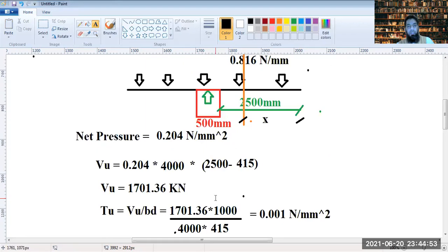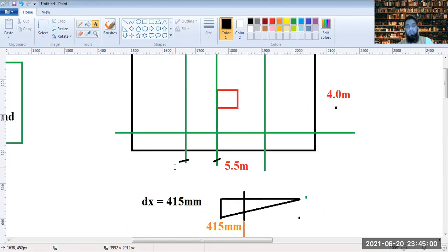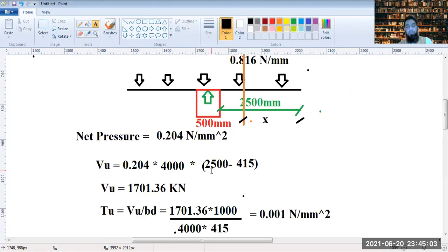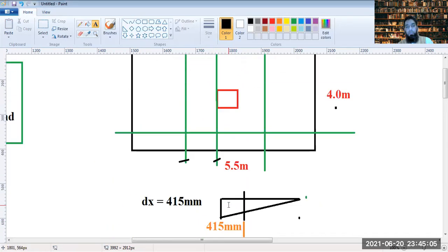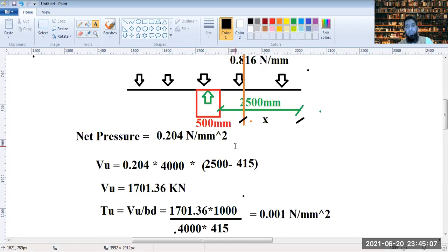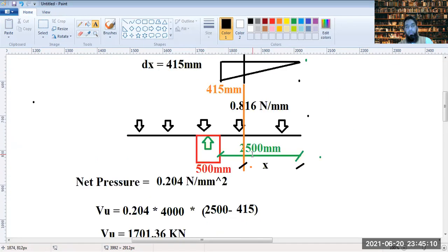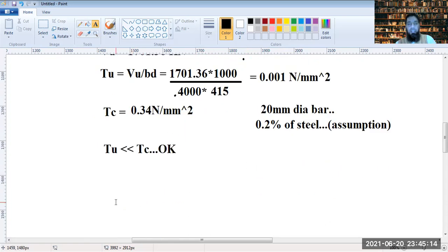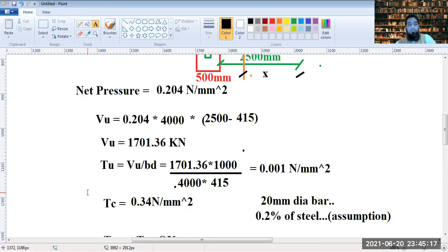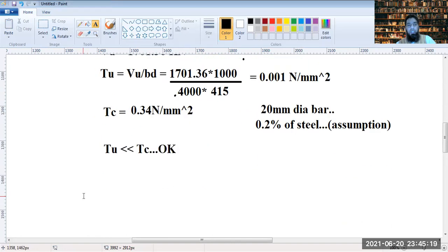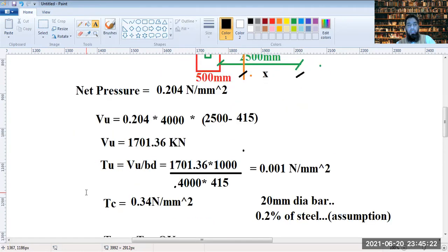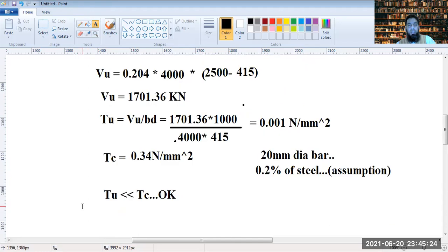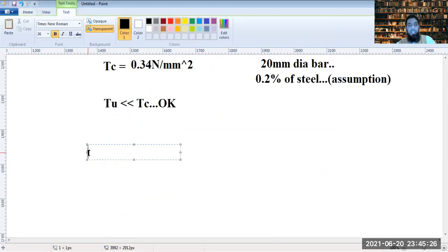Because this would be multiplied by 5500, but this value 25 would be decreased to less than 25. So it's naturally becoming lesser than this value. The shear forces are even decreased in the shortest direction, so we do not need to check that direction. So we next check for the two-way.